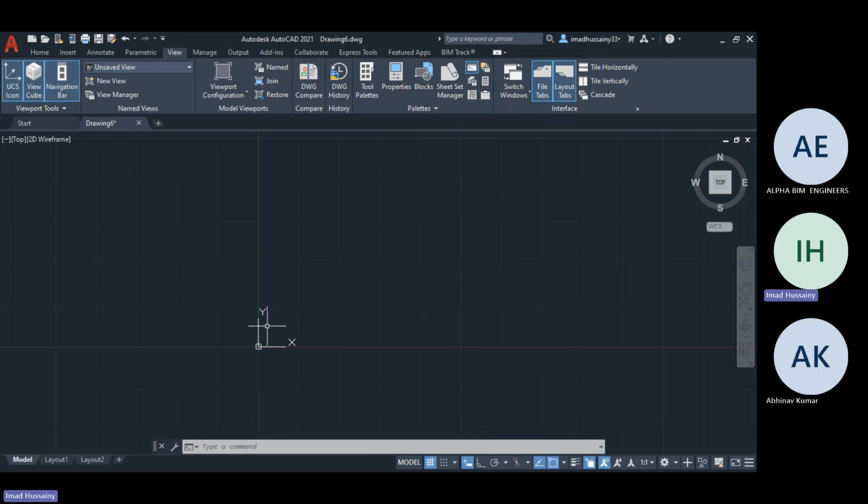I think this coordinate system will be a little bit confusing sometimes, but I think you have got the point what is UCS and what is WCS, right? Yes, sir. Yeah, but practice it. Try to move and try to draw a line. Once you draw a line, L enter directly. Enter means space button. Directly, you will get 2 points. If you don't have, just activate this dynamic input.